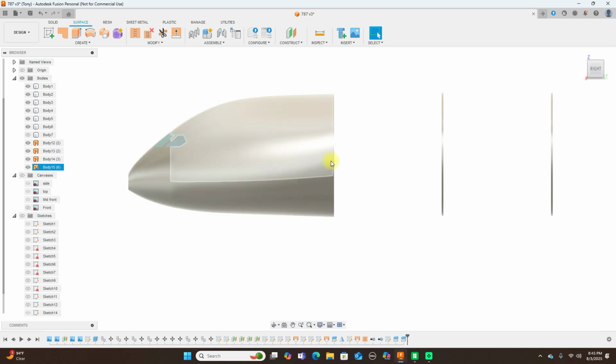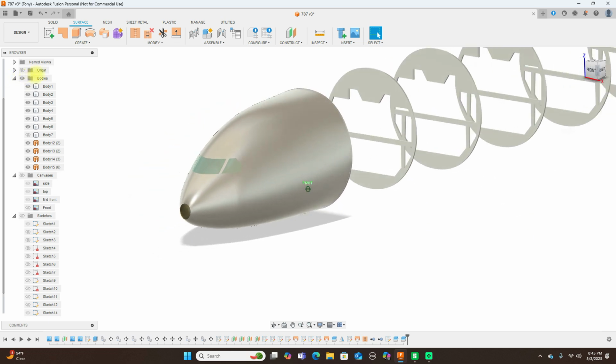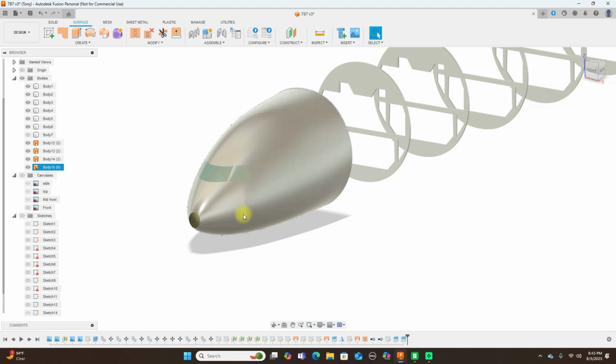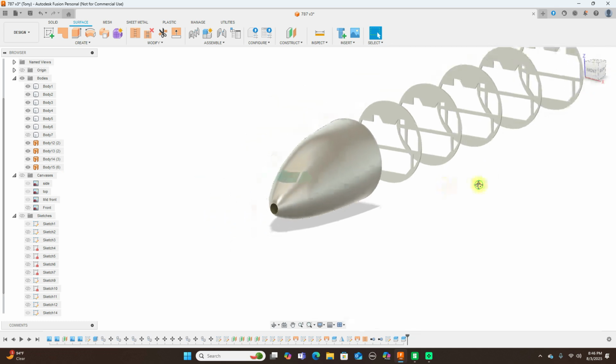What you should do is do all of them together so this is just one piece. And that will give you a nice transition between the whole thing. So you won't have this small little hump here. It'll be a nice smooth transition, lofting all of these together. But to do that, you're going to have to make sure your rails are all connecting on each one of these sketch profiles that you did.